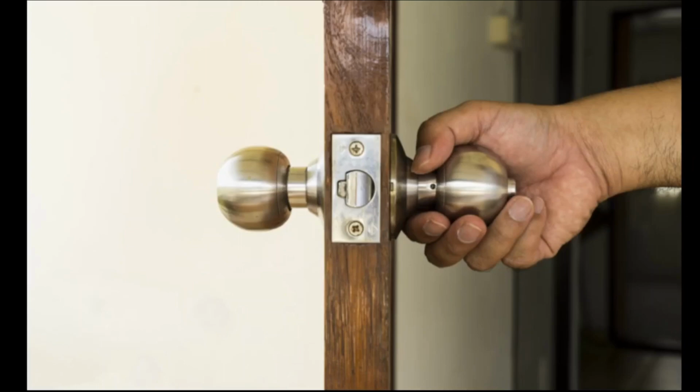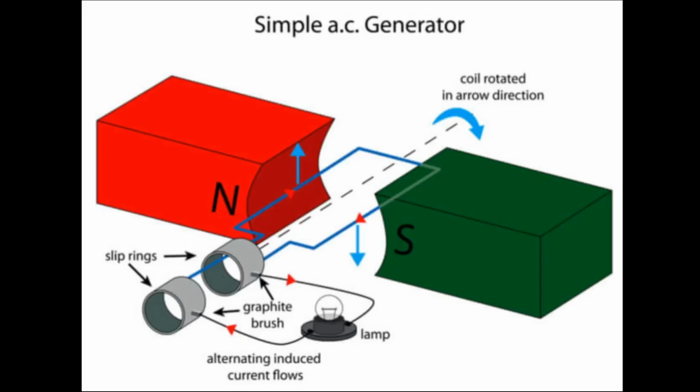So with that same idea, when the angle of motion is 90 degrees, then the induced current will be the greatest. Keep in mind though, it's the angle of the motion, not the angle of the coil, not the coil's position that should be 90 degrees. When the coil is horizontal, its position is parallel to the magnetic field, but its motion will be perpendicular to the magnetic field. Perpendicular meaning 90 degrees. That special angle of 90 degrees is where you have the most induced current.